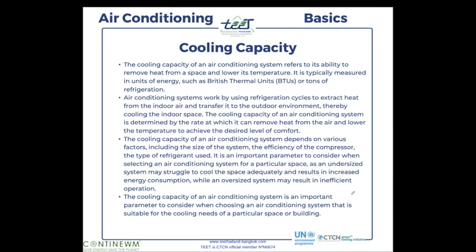It's not always easy because sometimes you are in a small area. I'm thinking about a test we did at one factory, where we were in a separated building, just like a small house made of bricks, with a lot of windows, single layer windows, and a metallic roof under the sun. A lot of heat. If this same room was inside the main building, in the middle of the floor, with the same air conditioning, the cooling capacity would be good enough.